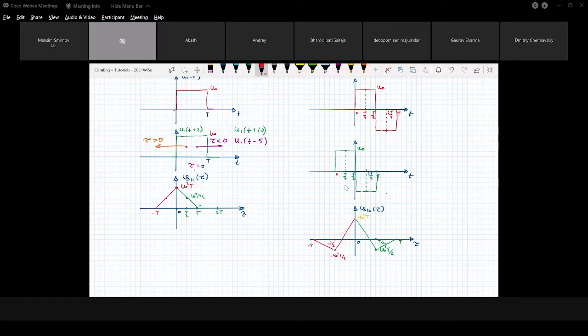Okay, fine. And what else do we need to calculate? Yeah, this is all for part A. It's the question where we need to determine the autocorrelation function for each signal. And also we usually specify superscript E. It means that we're working with energy signals, because when we start discussing periodic signals, if we use the same procedure, we will get an infinitely large correlation function.